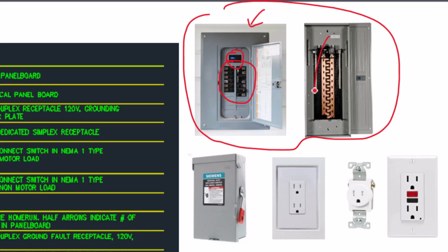And the inside of the panel board, when the circuit breakers are removed, as well as the cover, looks like this right here. The copper is the energized portion, so the wires would come here, there's screws, and then you would basically connect the hot legs. This could be phase A, next phase you could consider phase B, and then you would basically energize these copper buses inside the electrical panel.